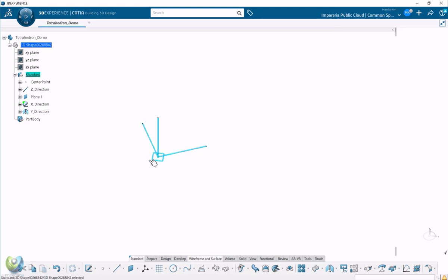Always make it once like this. You can create it as a power copy, so you can use it anytime, anywhere. Once you define it, you can change the location, and all your model will follow your axis system. It will avoid the errors when you want to move something. Sometimes you will encounter errors.